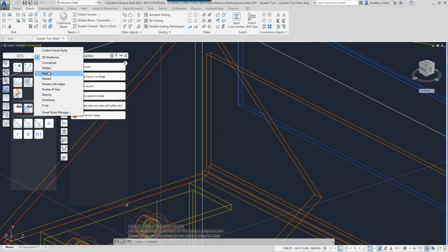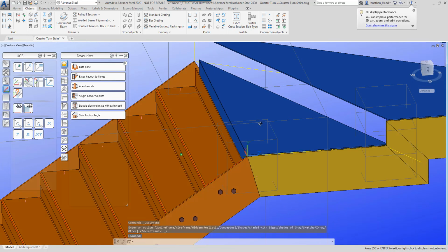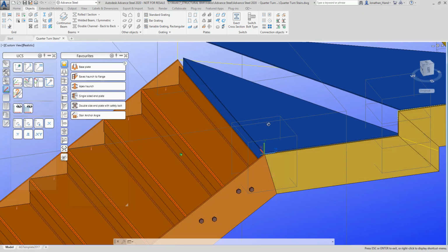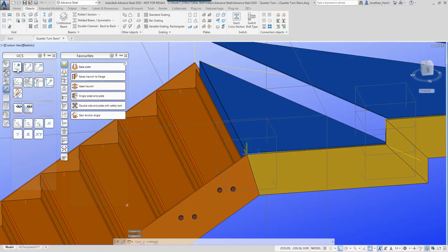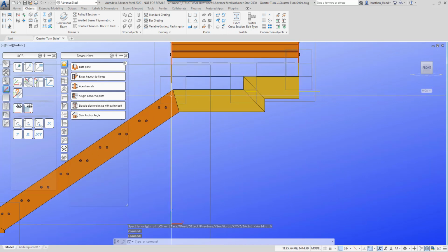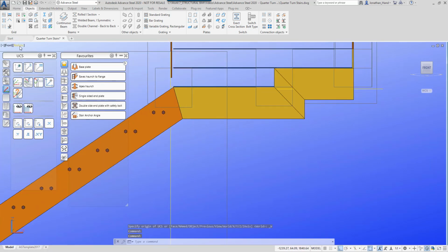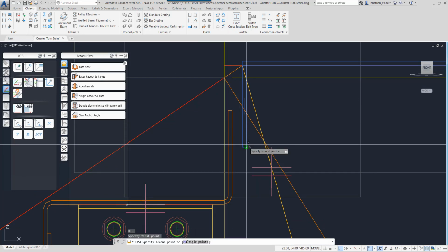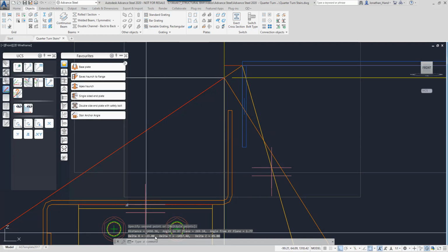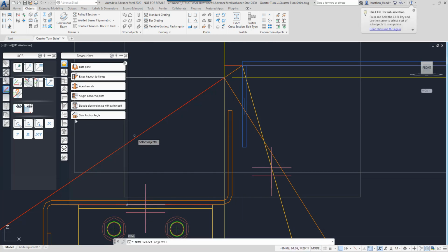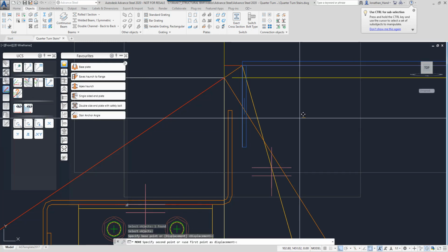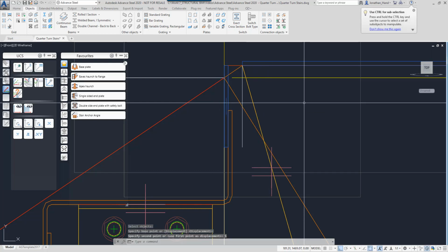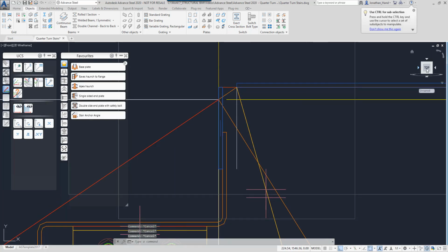We have a quick look, and you'll see I've got my plate drawn into position. And then if I just look onto the side section, so let's set the UCS to 0, let's look on from the side, and let's go into wireframe. So what I want is I want this plate at the front, so I'm just going to measure a quick distance from there to there, and you'll see that it is 23. And if I just UCS to the view and move that plate 28, which includes, actually just move it 23. So what we can now do with that in position,